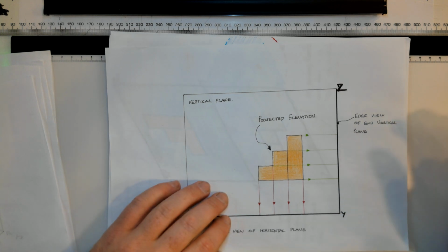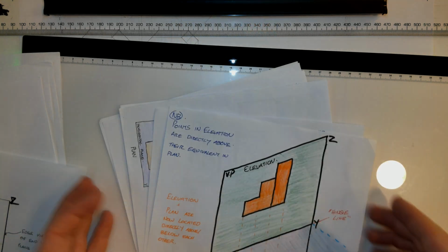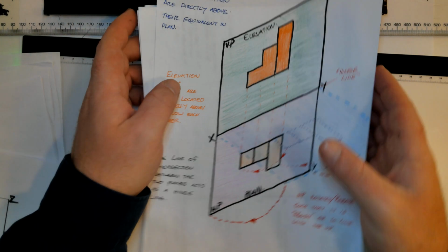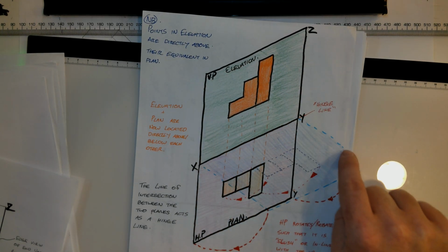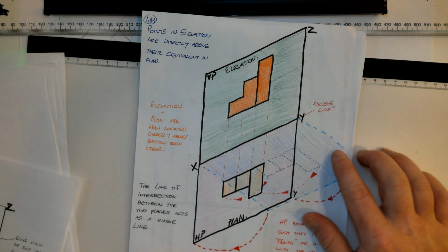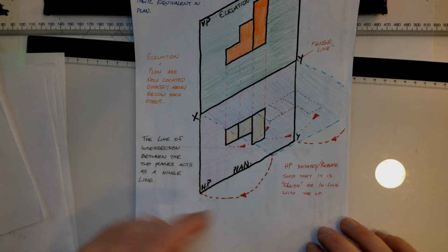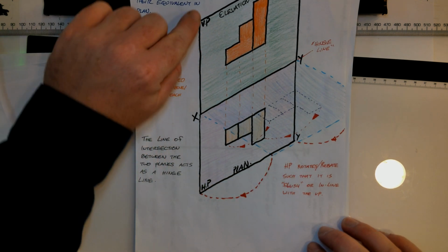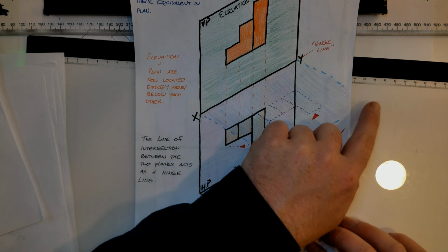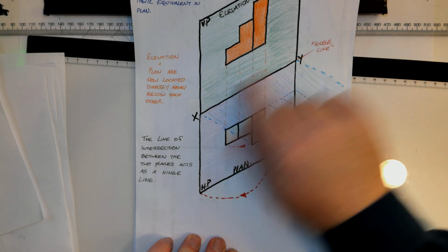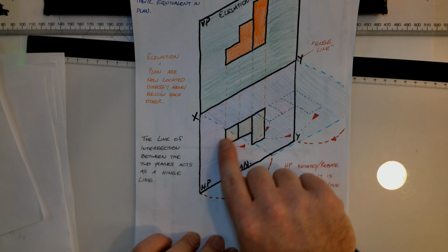So what happens there, if we look at this next sketch, I'm going to have to rotate the sheets. If we look in this direction now, we have our vertical plane, and we had where our horizontal plane was. You can see it dotted here. What happens is, we get the horizontal plane, and we hinge it down so that it's in line with our vertical plane. So you can see these lines of rotation. Can't really see the corner here because there wasn't enough room. So we have the hinge line, which is the XY line, the line of intersection, and this rotates down so that it's in line, and then we see this plan.